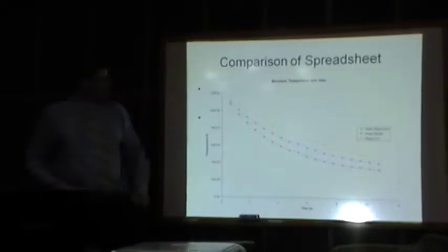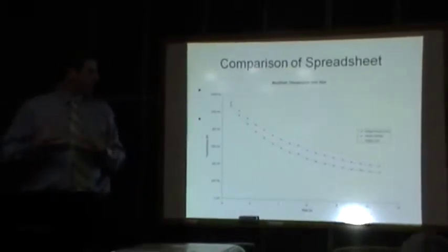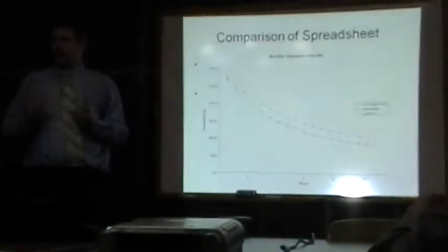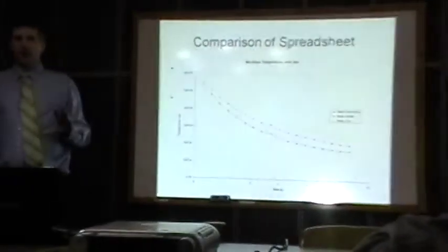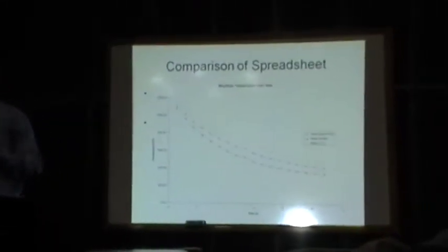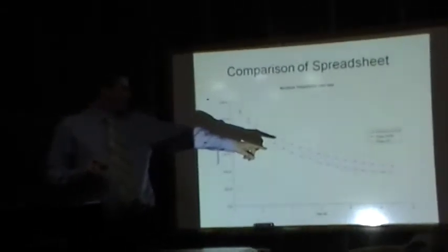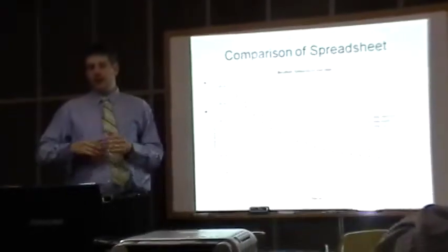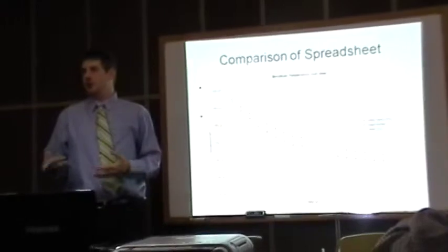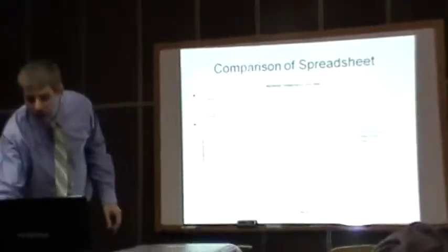Now, there was some error at around 11 seconds, and that was because of my assumption that it is a gas the entire time that the blowdown occurs. What RELAP 5 was telling us was that at that point you're starting to get to the triple point of CO2, so you were getting multi-phase flow, and thus it errored out.